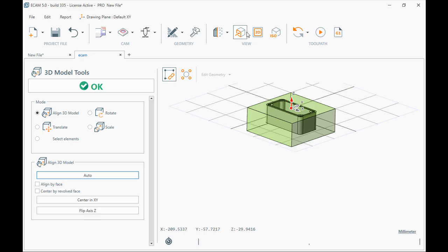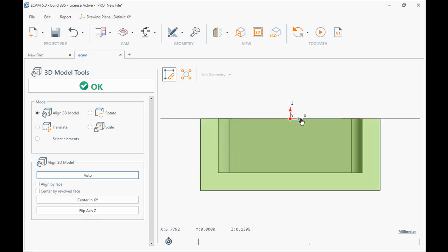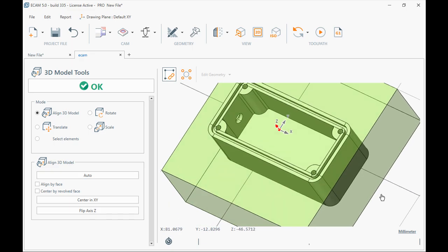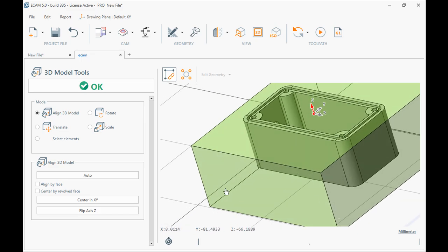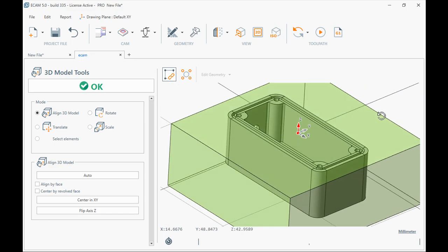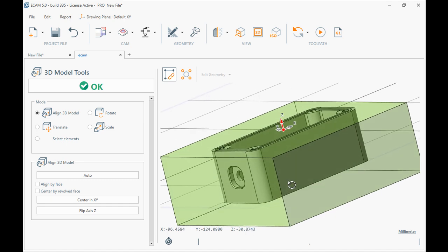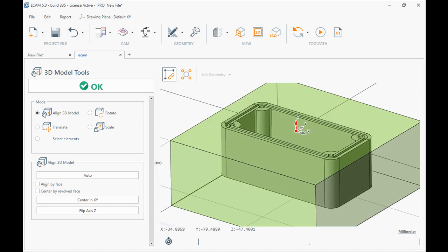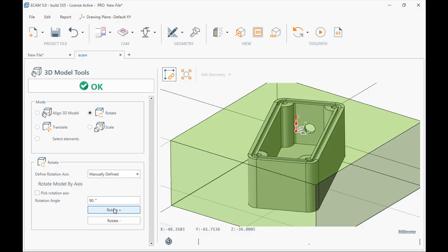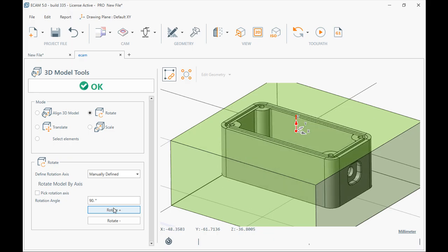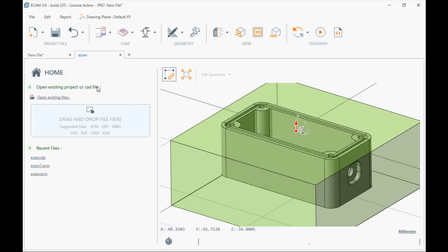And okay, very good. Z0 on top surface, perfect. And oriented in the middle, which is what we usually need. On this side we have a small box, so I'll make now a manual orientation to turn the box here. And that's it.